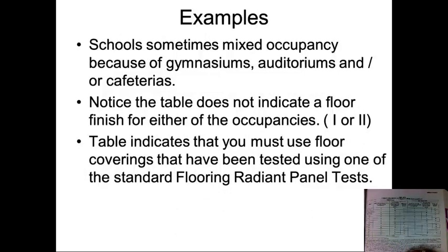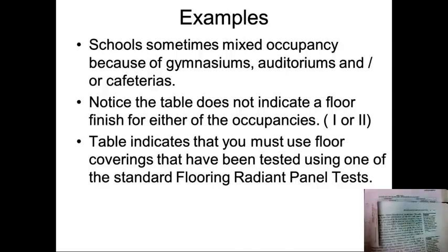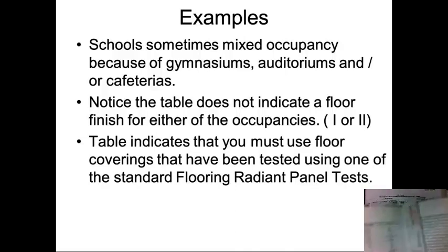Schools sometimes have mixed occupancies because of gymnasiums, auditoriums, or cafeterias. So notice the table does not indicate a floor finish for either occupancy 1 or 2. So it's not telling us in here what our floor finishes are. How do we go about trying to figure that out? Those are things that we need to look at, because remember, back in your textbook, in your Life Safety Code book, this is where we're going to look.